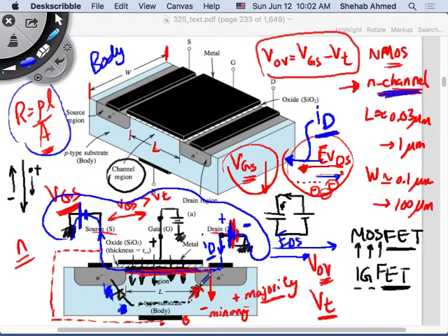And here, also when this was grounded, it was not forward biased. It had basically 0 volts across it. Ground was at 0, the body was at 0, here was at 0, it was not forward biased. And then when I added a positive voltage here, this became more reverse biased, right? It became more positive here than negative. So now both diodes are reverse biased. You cannot forward bias the diode. If you do that, then you don't have the MOSFET effect.